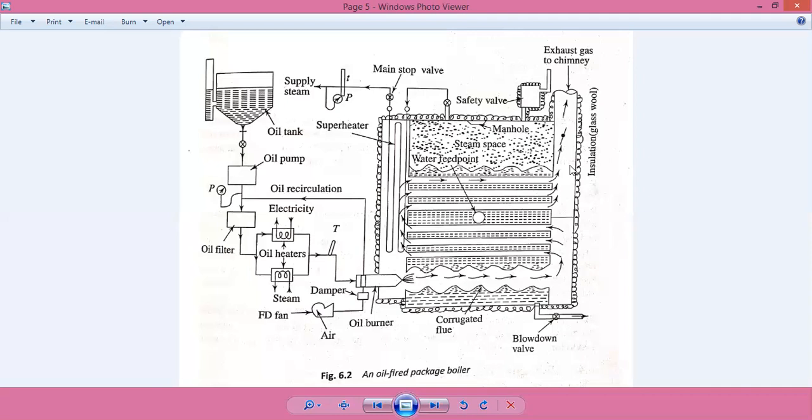But with coal, locomotives full of coal are required every day to be moved for running each and every power plant itself. The main disadvantage of the oil fired internal tube furnace in comparison to the coal fired one is that oil is much more expensive in our countries, and sometimes it limits your economic use because you cannot increase your power tariff beyond a certain degree. Thus this type of oil fired furnace is mostly used as a stopgap furnace where there is a certain high load, to run for a few hours and then stop it again when the demand is met. So the use of the oil fired furnace is directly taken over by the coal fired furnace.